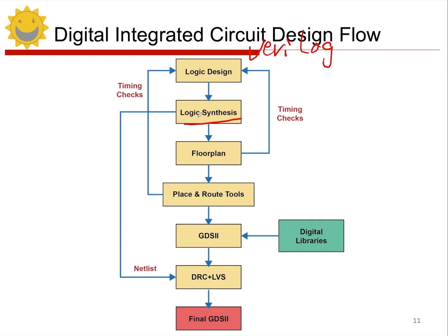By using Verilog, we can articulate complex logic designs in a structured and standardized manner, which is crucial for further processing. After we write it out, we move on to logic synthesis. The purpose of logic synthesis is to convert the functionality described in Verilog into a gate-level netlist. This means that what was originally a language description can now be translated into a circuit structure made up of actual gates, which can perform the operations we initially described in words. Logic synthesis is a critical step because it ensures that the abstract logic is accurately represented in a form that can be physically realized.